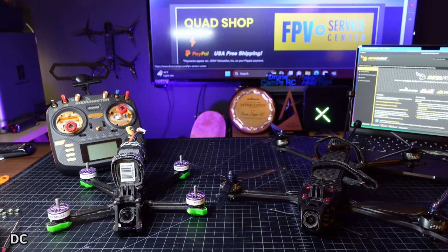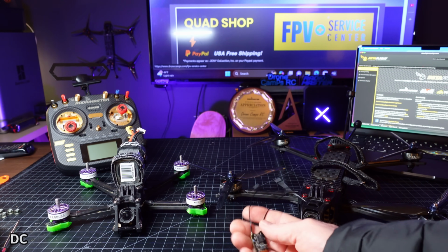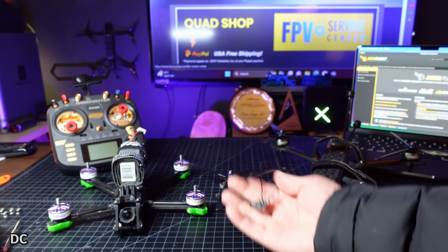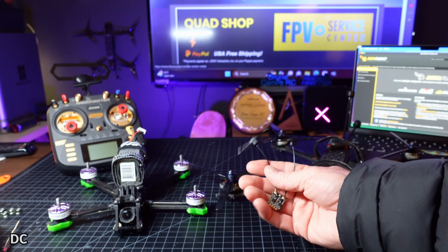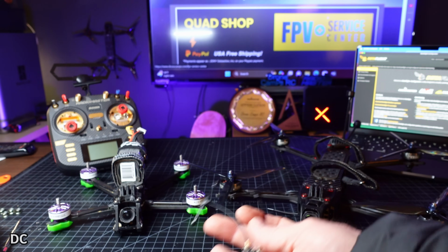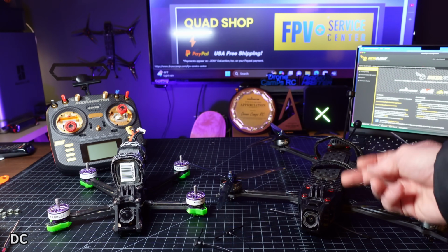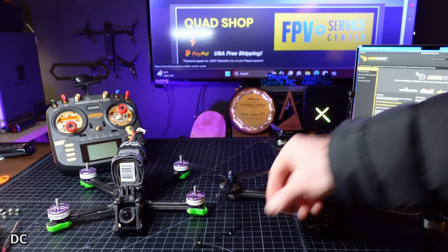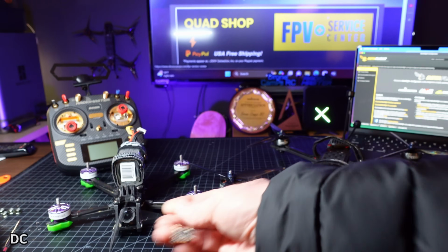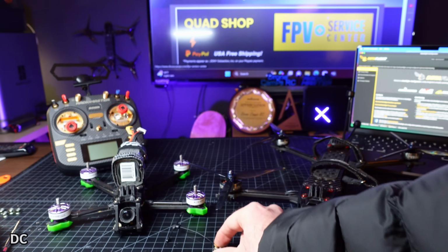Now, if you want to mount, say, a diversity type receiver, you can do that. TBS has them, ELRS has them. This is the new ELRS receiver from Radio Master. This is a great one. It is true diversity. You can mount one on the vertical and one on the horizontal. So bring one facing up and then bring one facing across on your quad. And sometimes it's good to try to get them a little bit of separation. So spread them apart as far as you can, and that'll give you the most coverage on both of the axes in the spectrum.